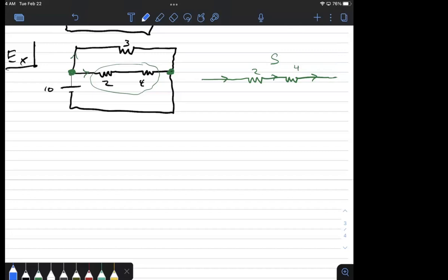So what I'm going to do is I'm going to say, look, I want to take this circuit and make it look like this. Okay, this is easier. This top path is the same. I haven't messed with that, but the bottom path I'm changing. Right now, this blue circuit, this equivalent circuit, is easier because there's just 2 resistors, and those 2 guys are going to be in parallel. The top circuit is more complicated. I can't just do parallel sitting there.